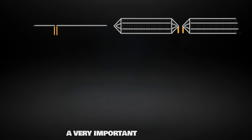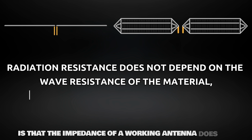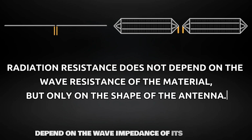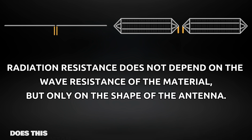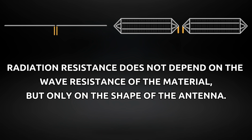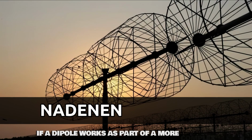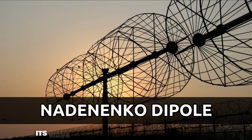A very important conclusion drawn from these experiments is that the impedance of a working antenna does not depend on the wave impedance of its element. But does this mean we can completely forget about the wave impedance of antennas? It turns out no. If a dipole works as part of a more complex antenna system, its wave impedance plays an important role.